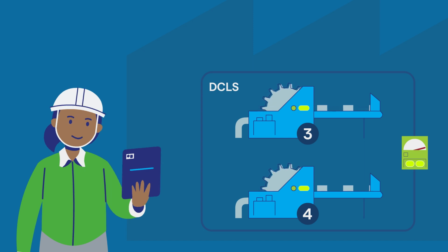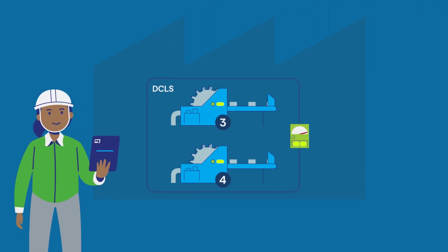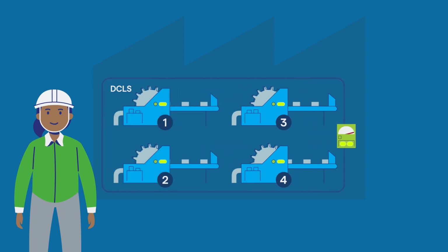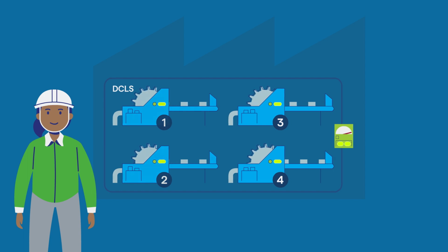In her application, she indicates that the machines at her factory are binary loads, meaning that each machine operates either at 100% of their capacity when on, or 0% when off. These details allow the system operator to schedule the load correctly. Note that the DCLS configurations are decided by each participant based on their business. Even process critical machines could potentially be okay as part of dispatchable demand.